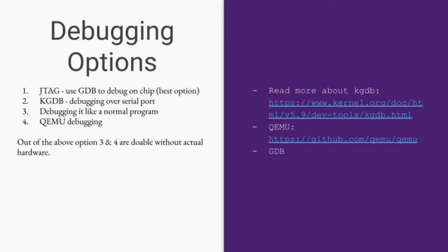And then there's also another option where you actually emulate the hardware. You can use QEMU to emulate an actual chip. For example, if you compile for Cortex-M3, you can emulate Cortex-M3. There's a number of boards that are supported by QEMU, which you can use as your build targets. And that gives you a system that behaves a lot like the real system.